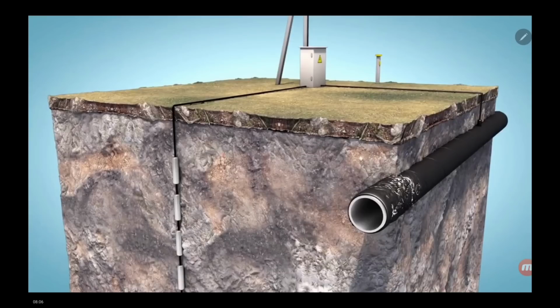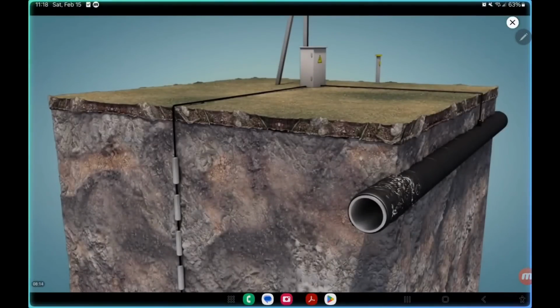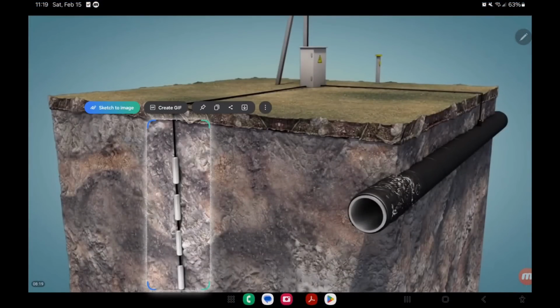Here we manufacture or design ground beds with steroids, if you want to put it that way. Because when we make this configuration, and mind you, sometimes we have to install this system 100 meters deep, 200 meters deep, 300 meters deep, because that's where the resistance was suitable for us. In the calculations and field measurements, it showed us that the resistance at that depth was the most suitable for